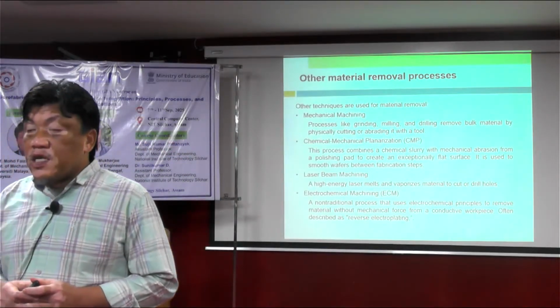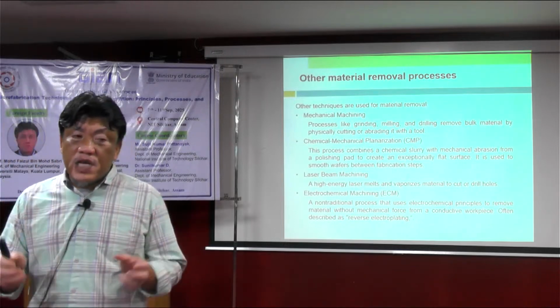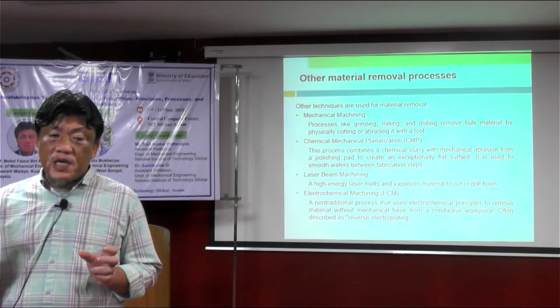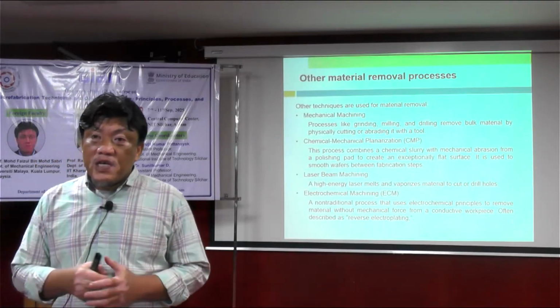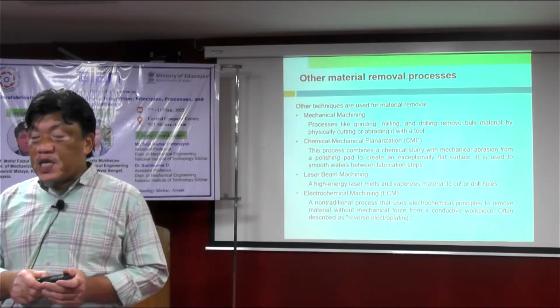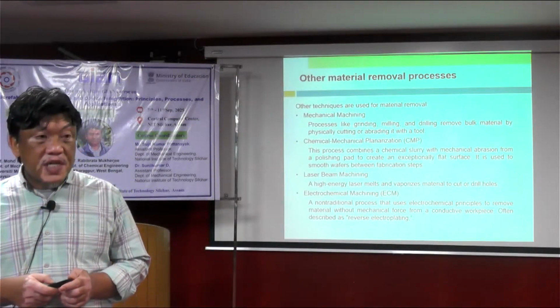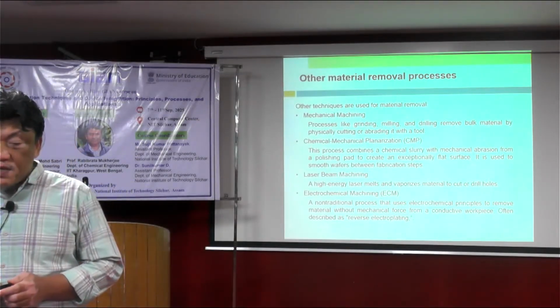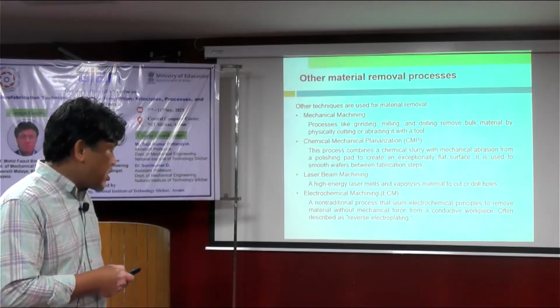So with the reverse use of electrodeposition, we know that one side will be removed and one side will be deposited. So in a way, it can be a removal of material as well: etching or removal of material on the anode side of the electroplating or electrodeposition setup.